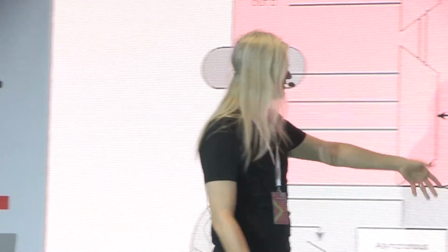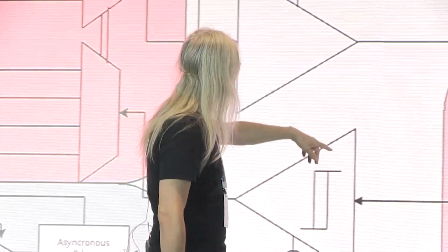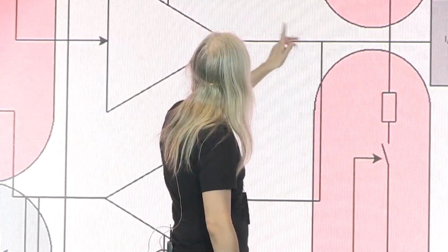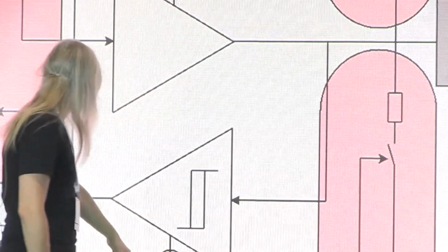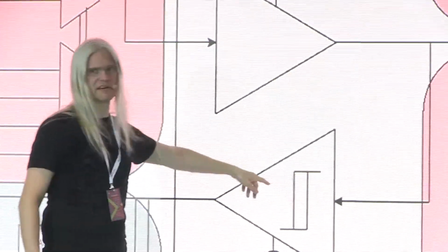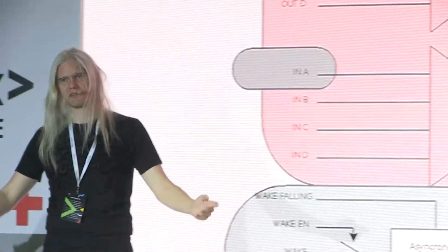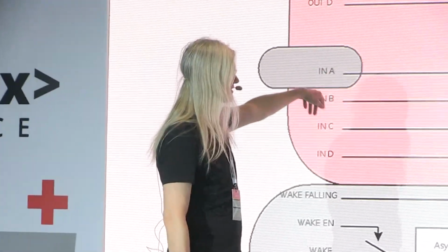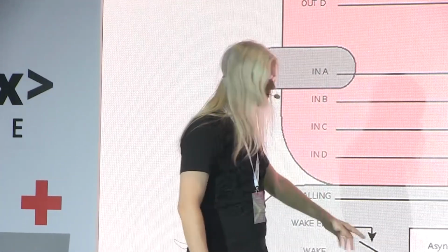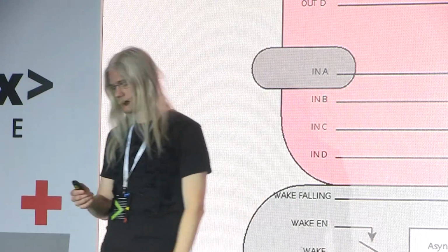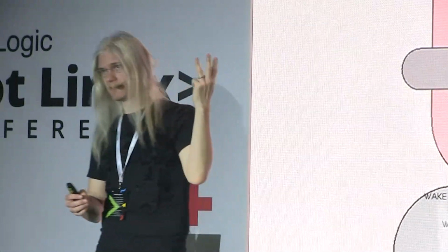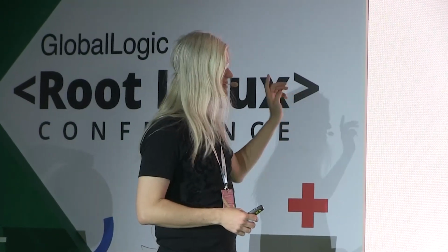Pull down with the depleted transistors here. Pull up. Hysteresis control. You turn on this Schmitt trigger here. And the asynchronous and synchronous edge detectors. What do we do with them? Yeah, they go into other subsystems. So the pink stuff goes into pin control, and the blue stuff goes into the IRQ subsystem. So you find 3 different subsystems in the kernel that deal with this. There's GPIO, there's pin control, and there's IRQ chip.